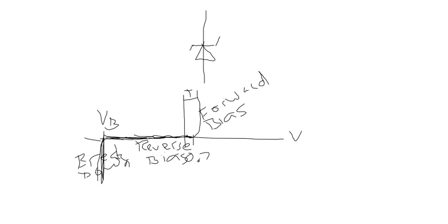And you can get Zener diodes that have pretty much any breakdown you want. For smaller voltages, I think they go in steps of like 0.1 volt. You can get like 1.5, 1.6, 2.7, 2.8, and up to a point of about 10 volts or so, it may start going in a little bit bigger steps like 10.2, 10.4, and so on. But you can get virtually any breakdown voltage that you want.